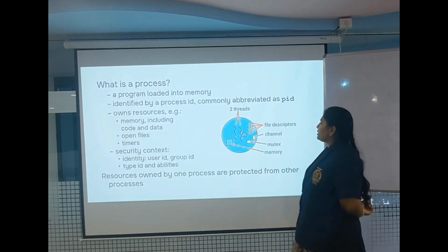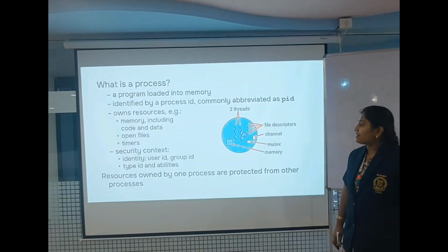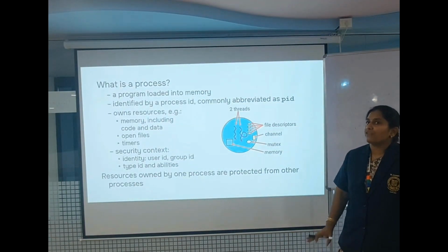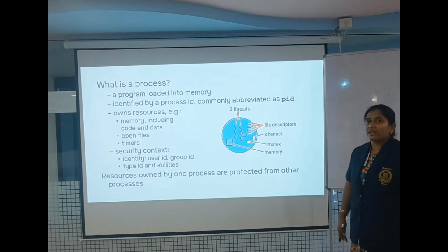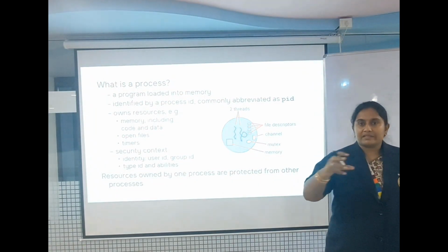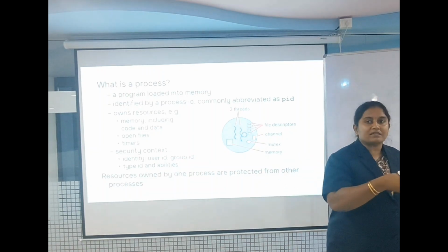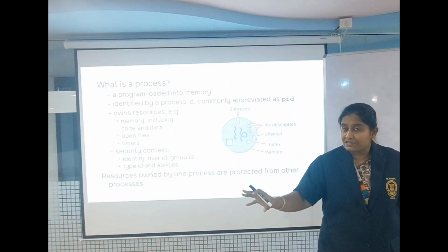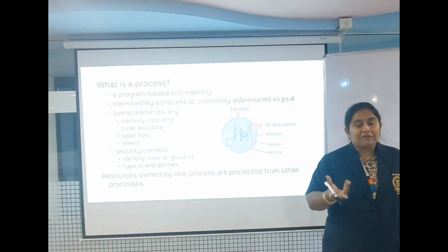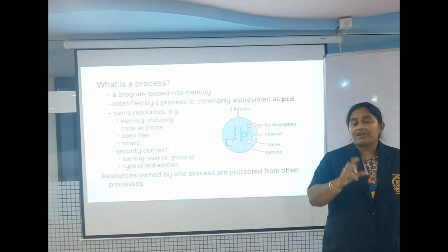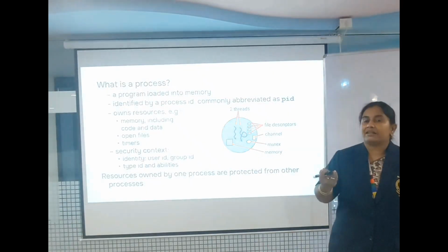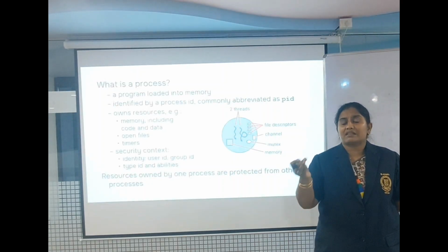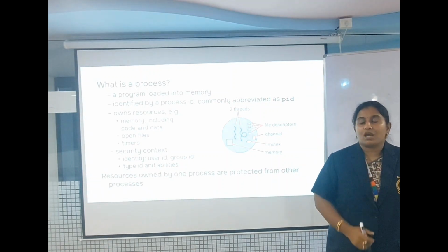So in the security context, you can see every process has an ID and every process has a certain set of abilities, which is configurable in a QNX operating system. Like how in a Windows system we have users and privileges, similarly, in an embedded system, we have several processes. Each process has an ID, and every process has a set of resources like memory, files, hardware requirements like timers, etc. Also, every process has its own abilities, like whether it is restricted to a particular application, or whether it is able to call the kernel space. There are some attributes which are configurable with respect to the process.